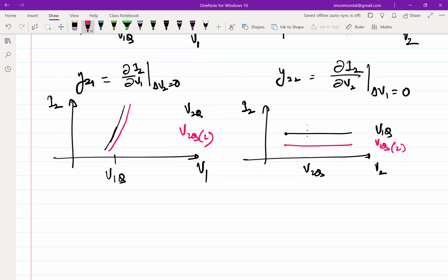Even though I haven't talked about semiconductor physics and how things change, we should at least appreciate the fact that if your temperature, humidity, and everything changes widely, you cannot expect everything to remain constant. So IV characteristics tend to change. Because they tend to change, you don't want a device which works very well only at a small bias point. You would like to have some leeway.